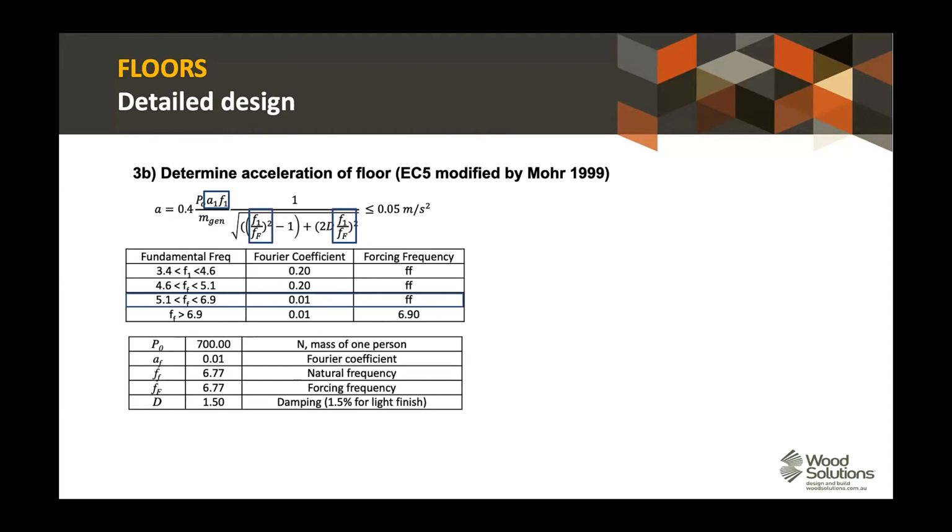One thing we have been doing on the side, this is a bit of a tangent, I apologise. You can get really good quality apps for free for smartphones which allow you to capture frequency response from the accelerometers in your smartphone and then download them as a CSV. And so wherever possible, we've been capturing data from as-built floors to try and help understand what frequency you actually end up with, and more importantly, what we can expect from damping.